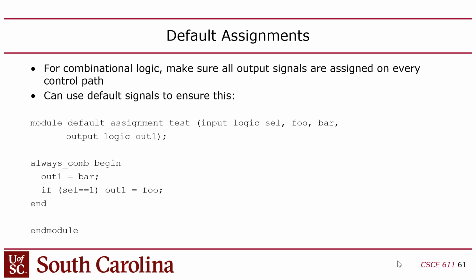Well, no, what happens is if you assign an output twice inside an always, the only one that matters is the last one that gets assigned, right? You guys with me? Because remember, with combinational logic, the goal is you're basically building a truth table here, but you're doing it in a more productive way than writing out a whole truth table. Does that make sense? Okay.